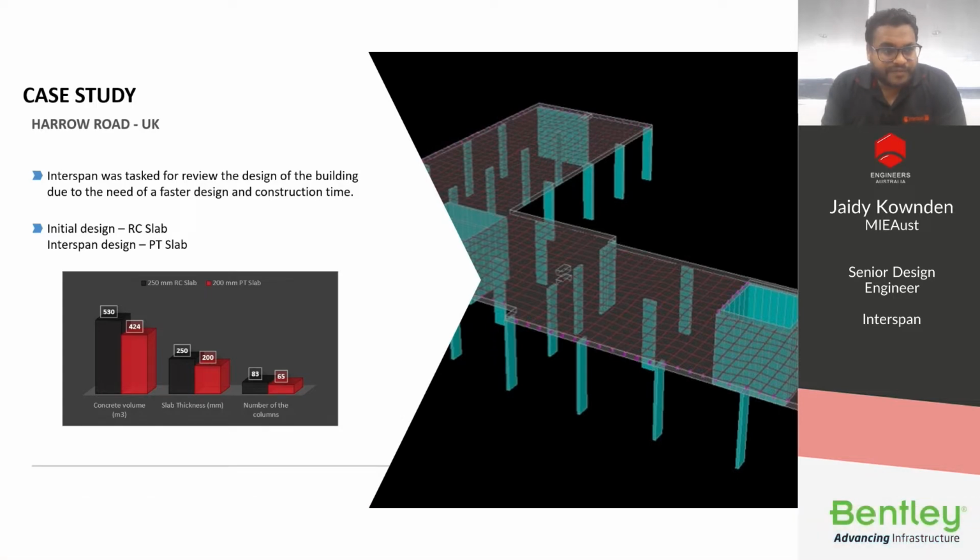We have saved the amount of concrete. We have reduced it by over 100 meter cube, and we have reduced the thickness from 250 to 200, and we reduced the number of columns that we use from 83 to 65.